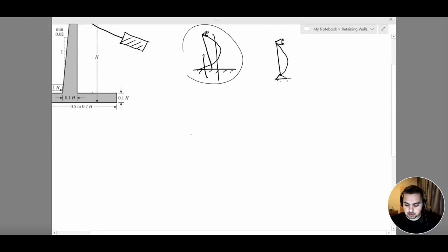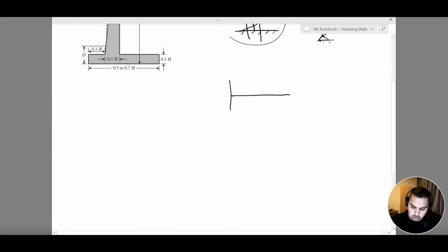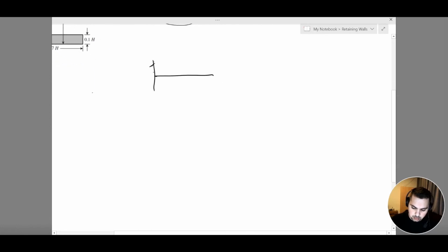What we do is draw a beam element which is fixed from this side here, and has a roller from this side, and we draw a uniformly distributed load that has a magnitude equivalent to Ka γs H. Now we find the bending moment of this model.